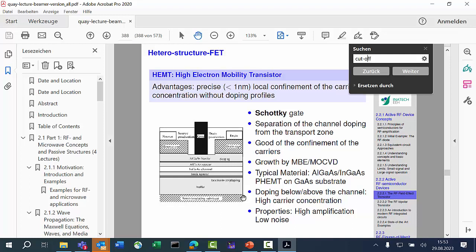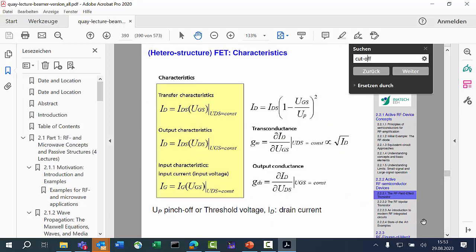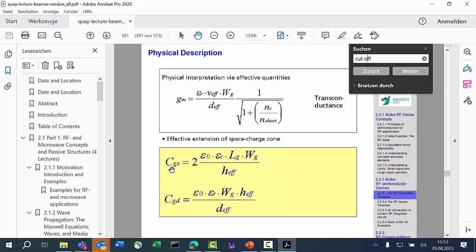That is not the original intention, but because they reduced the area, they were reducing the capacitances, which is the speed-relevant capacitance of the device. So by just making good memories and many bits per area to put into your pocket, you also win something which is extremely fast. So that's why the CMOS memory chips are also very good RF transistors.